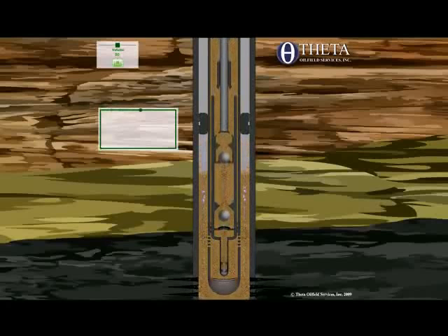So the liquid goes in, down, and into the dip tube while the gas is produced up the casing. The key to this design, of course, is to have the speed of the fluid be about 0.5 foot per second or less to give the gas a chance to escape. If the speed is higher than that, then some of the gas can be trapped and brought in anyway.